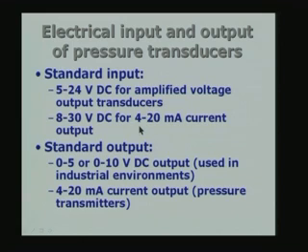If the output current is 0, that means there is damage to the instrument, that means there is some problem with the instrument. So, the way to recognize whether there is any problem with the instrument is to see whether it is giving 4 milliamperes when there is a delta P equal to 0 or not. If it is giving 0 for some reason, then you can immediately come to the conclusion there is some problem with the circuitry. So, I think we just had time to cover this much.